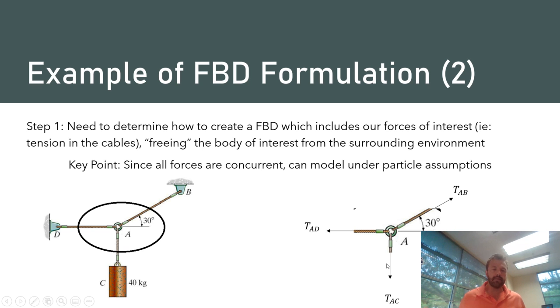Now, as we'll see in a minute, when we perform this type of analysis, we're inherently limited in the number of equations that we have available to us. In a two-dimensional or coplanar system, where we're dealing with the statics of particles, which we'll define more clearly in a minute, we can only write two equations. So because of that, we only have the capability to solve for two unknowns.